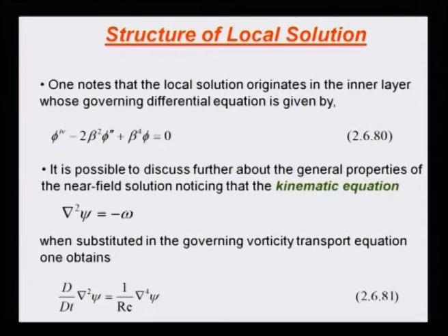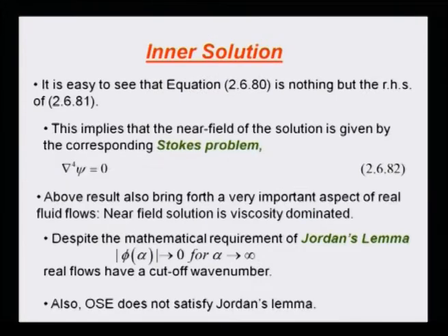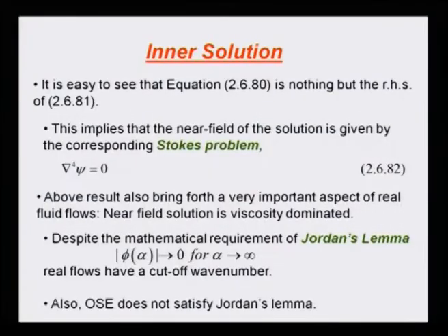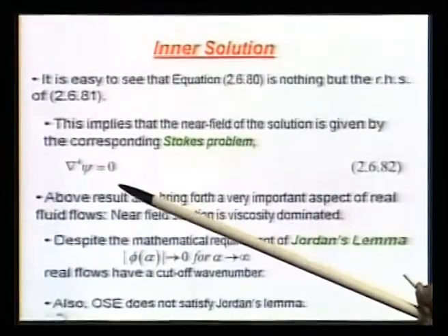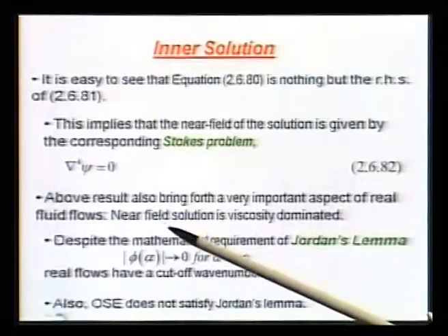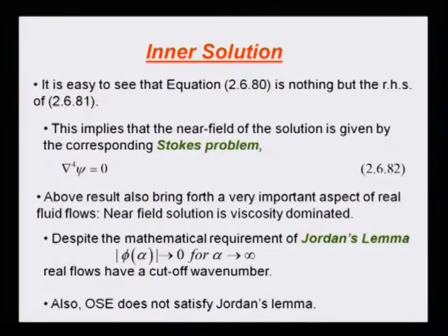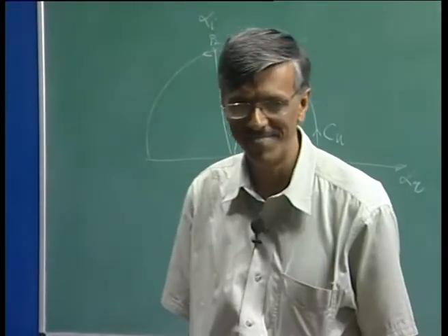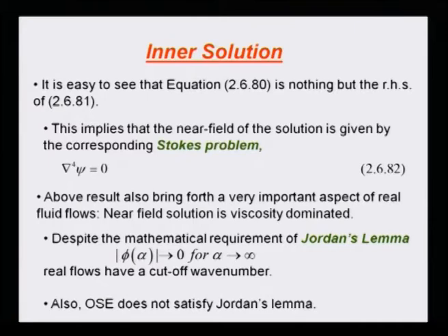We are seeing this very elegantly, that it's not due to some assumption. This is all coming from what we have done, that singular perturbation analysis. The inner solution reduces to the Stokes problem, that is del 4 psi equal to 0. So the near field solution is viscosity dominated because Re goes to 0.